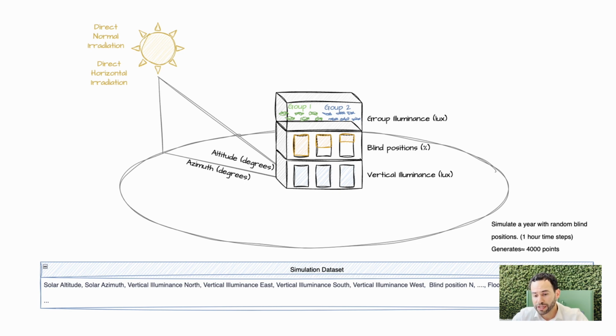And finally, we keep track of the values in the sensors over here. Let me point them out. So the illuminance, wherever we need it, which in our case is at the desks. We want this illuminance ultimately as our output. And then we group them, because typically you want to get an average of certain points in the same regions of the room.